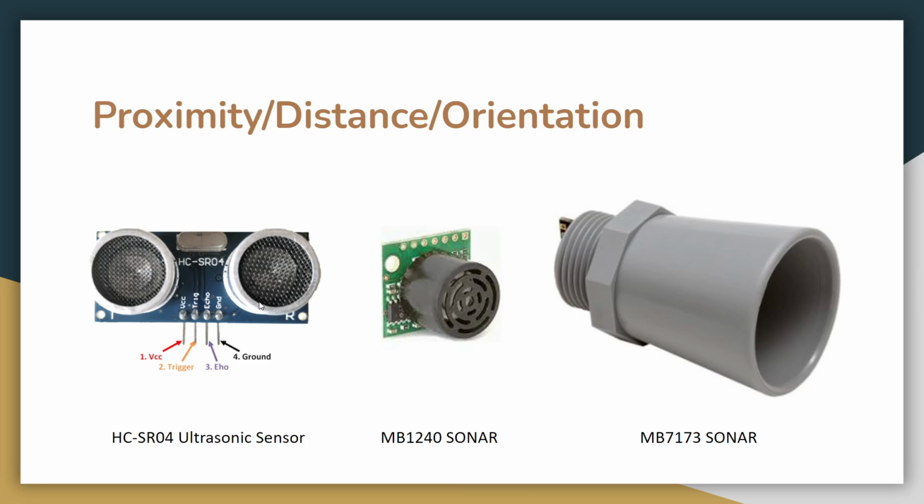Although there's one disadvantage of this sensor. Suppose I put an obstacle exactly in front of the emitter and block it completely, so that there's no gap between the obstacle and the emitter, or even if there's a minute amount of gap, that's fine. What's going to happen in that scenario? There's no space for the sound to reflect back into the receiver. Yeah, exactly.